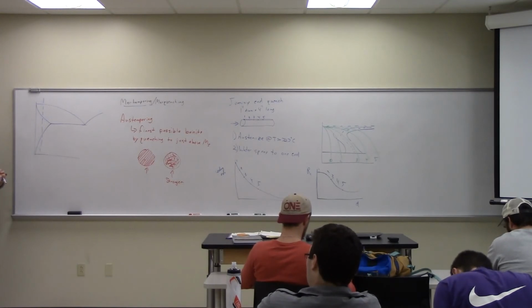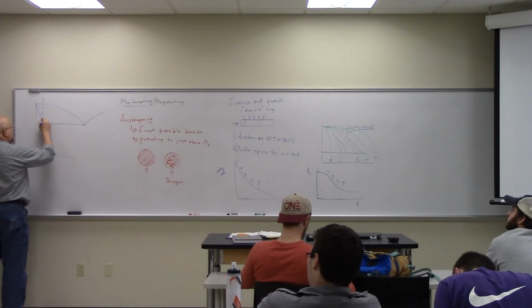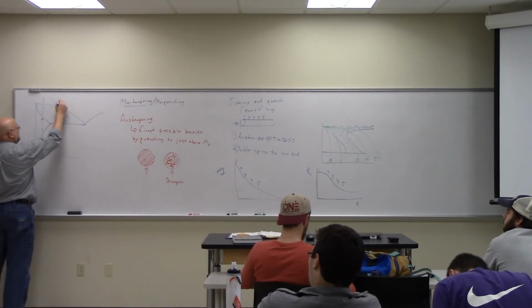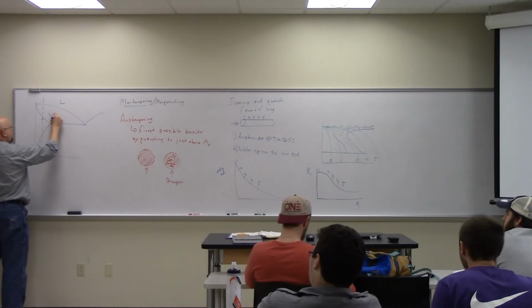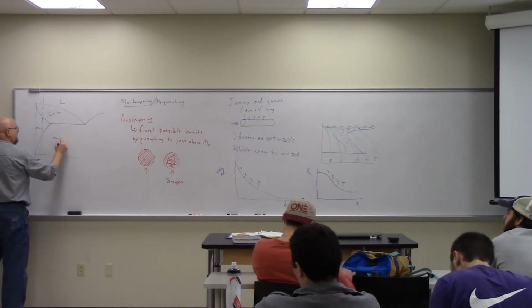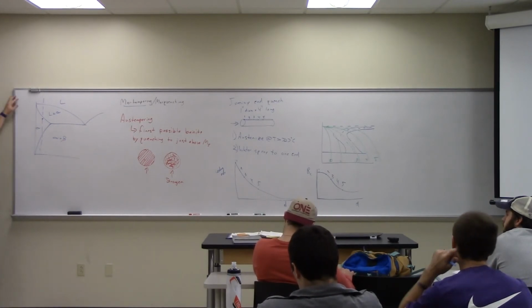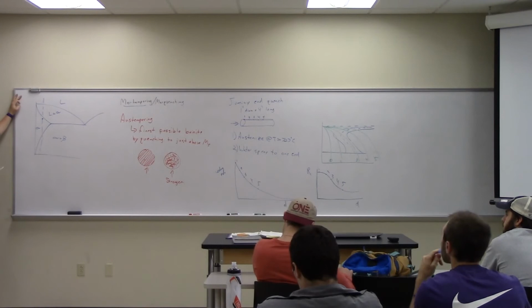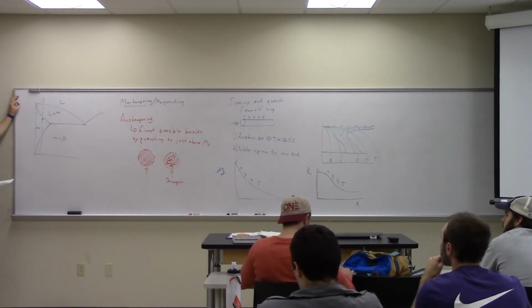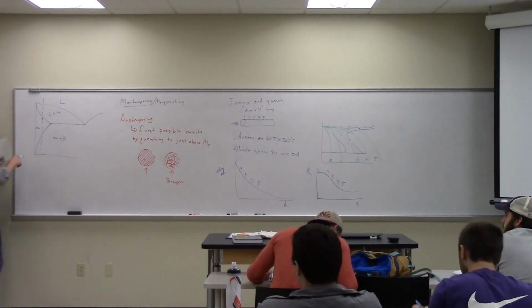So I have a material that's not going through eutectic. At this point, right here, what's the microstructure look like? Remember, this is, well, I'll just call it liquid plus alpha, alpha, alpha plus beta, okay, for lack of better definitions. What is the microstructure going to look like at that point? It's alpha, what's it gonna look like? And what am I gonna see? It's gonna look like crystals of alpha. Right, a bunch of grains of alpha. Great.